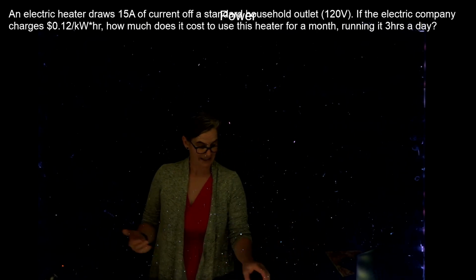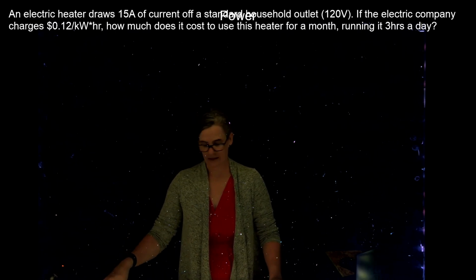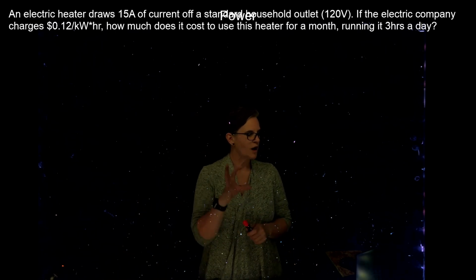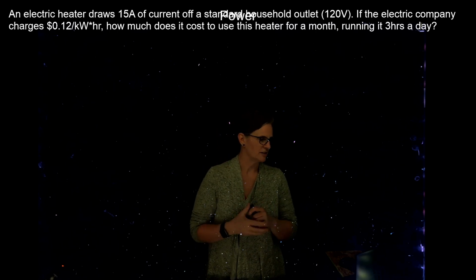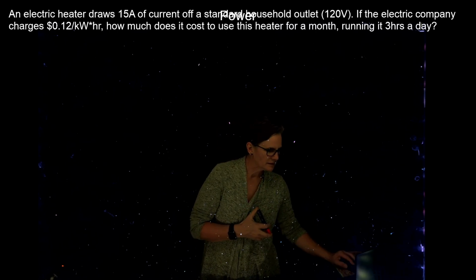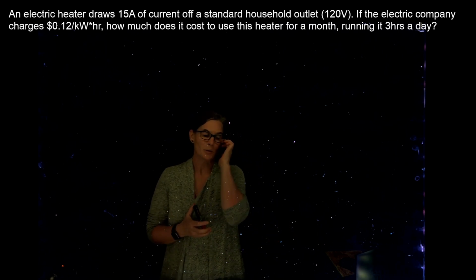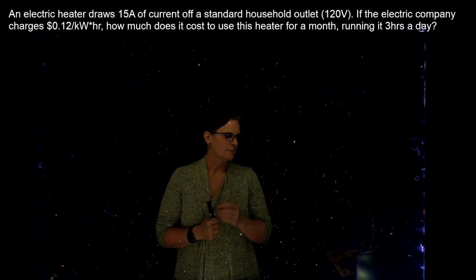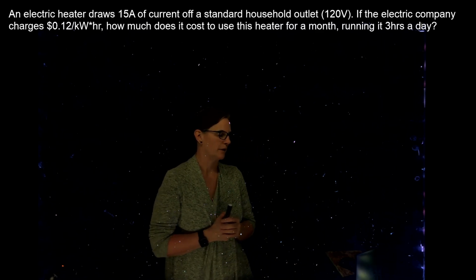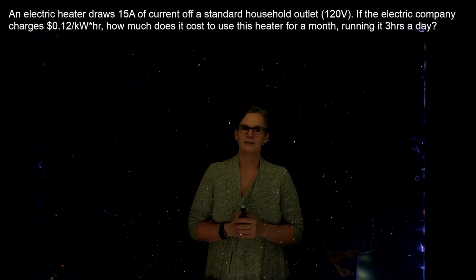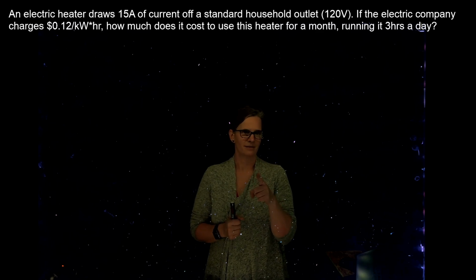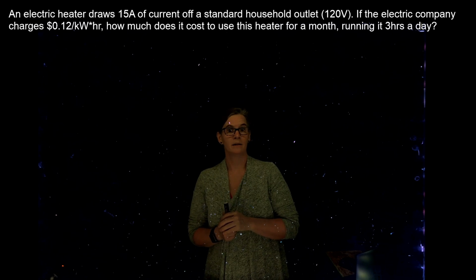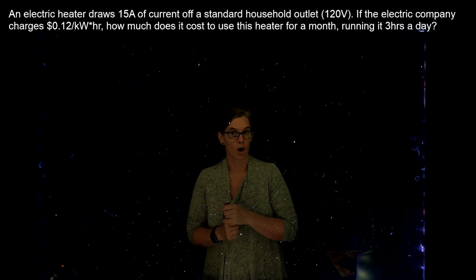An electric heater. It's summertime, so we probably aren't thinking about electric heaters at least right now, but if you're watching this in the winter, you might be. It draws 15 amps of current off the standard household outlet. So 120 volts out of that standard household outlet. If the electric company charges 12 cents per kilowatt hour, how much does it cost us to run that heater in the winter for a month for 3 hours a day? Only 3 hours a day. Maybe you'll appreciate why whoever you lived with said, turn the heater off or turn it down.